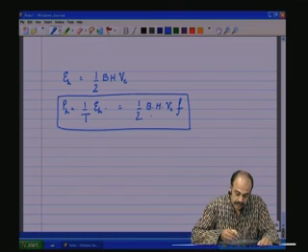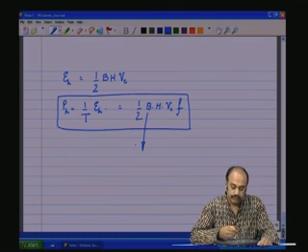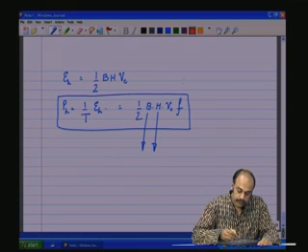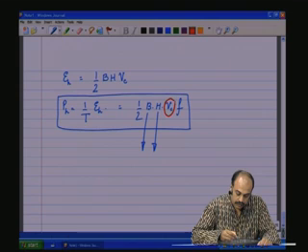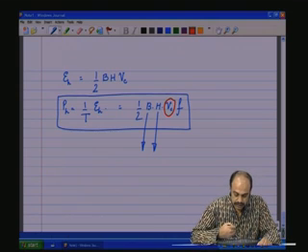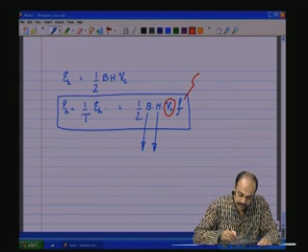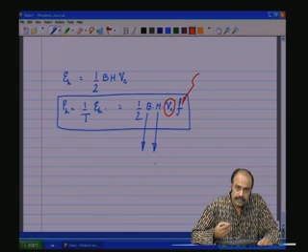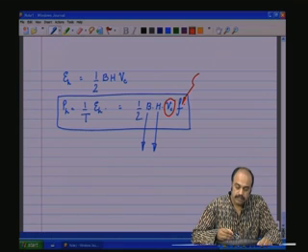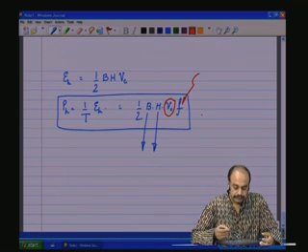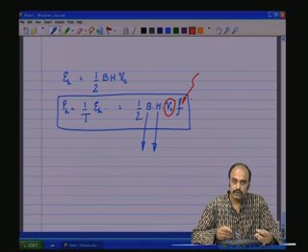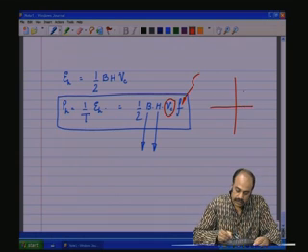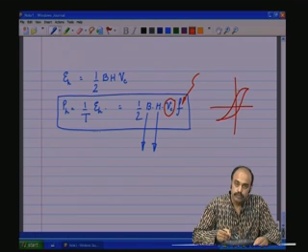See that the hysteresis loss is directly dependent on the flux density, the magnetic field intensity, and the core volume. Larger the core, more the hysteresis loss. Another important thing is the frequency of operation. As the frequency of operation increases, the hysteresis loss is going to increase. This is also in keeping with what we understand, because we are talking of the hysteresis loop.